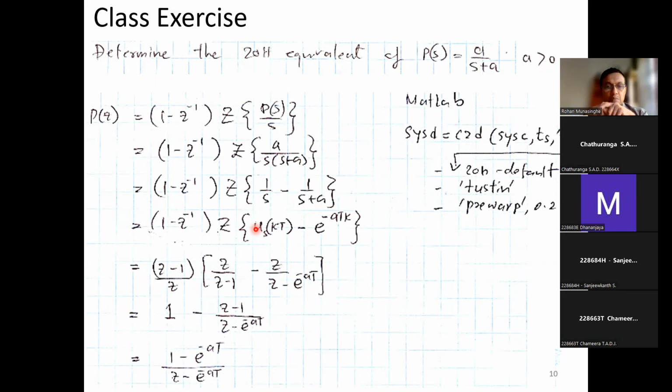So you write it down in the time domain directly, the sampled version. For 1/s, it is easier to convert into the Z transform. For 1/(s+a), in the Laplace domain, you know from the Laplace table that this corresponds to e to the minus at.